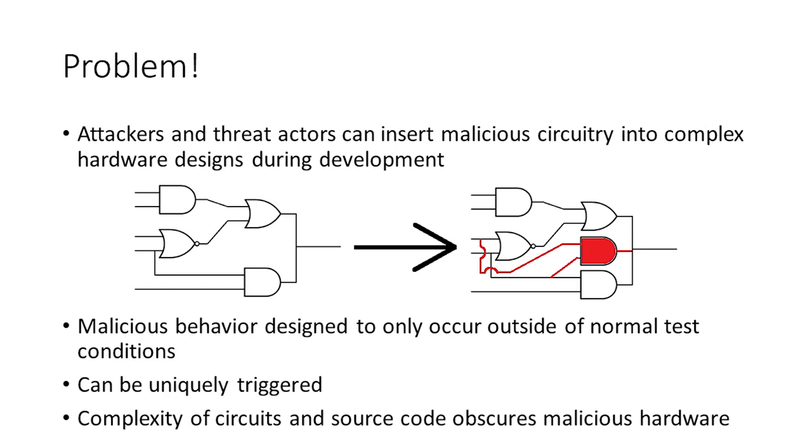Now, depending on the test case inputs that the system designers use to verify the correct logical operation of the circuit prior to deploying and fabricating it in hardware, the set of test inputs may not actually activate the malicious section of the circuit. So in other words, the malicious behavior is designed only to occur outside of normal test conditions, and the malicious behavior will not be recognized by the system designers because their test cases do not cover the set of circumstances in which the maliciously inserted hardware would activate.